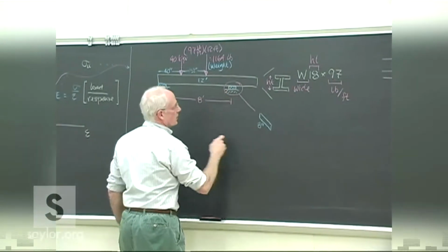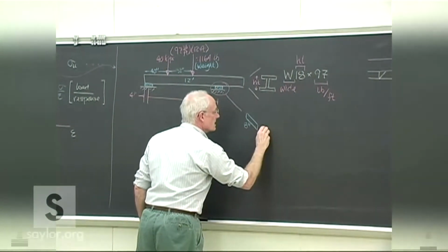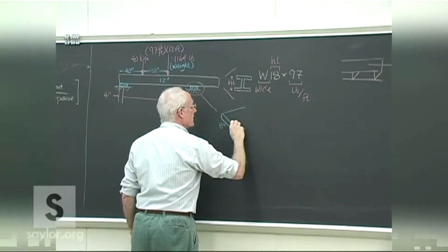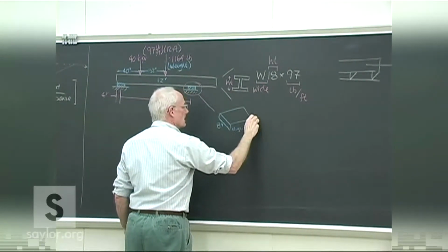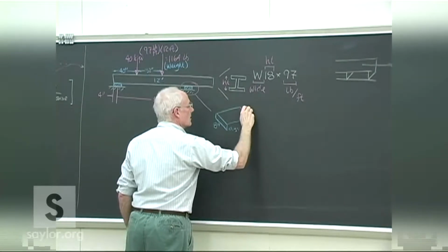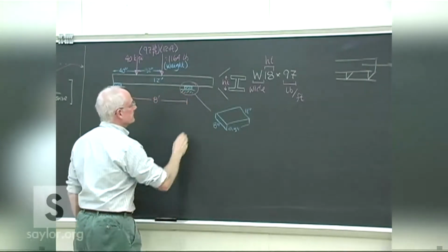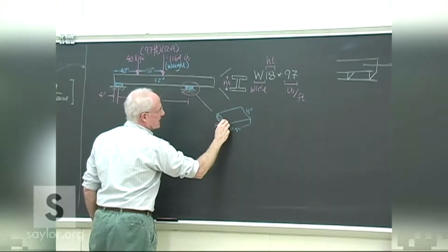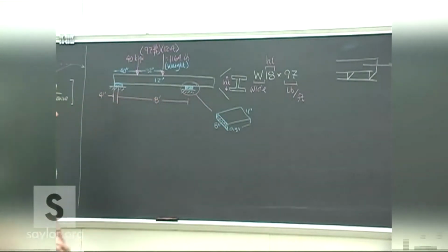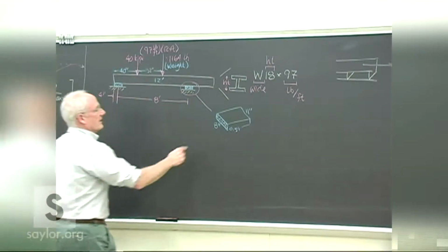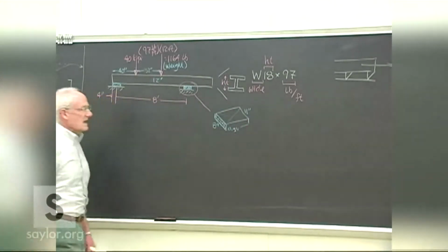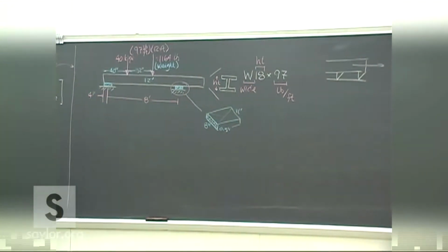So the front that we can see there is 8 inches by 1/2 inch, but then the pad itself also goes back about 11 inches. So this part we see there is the same as the part we see there, the 8 inches by 1/2 inch. And then the beam rests on this whole top area that's 8 by 11, half the size of a sheet of paper.